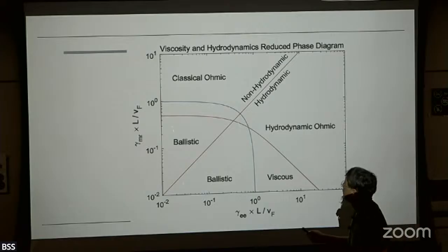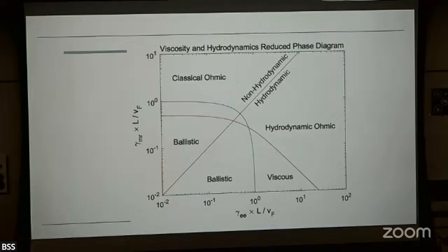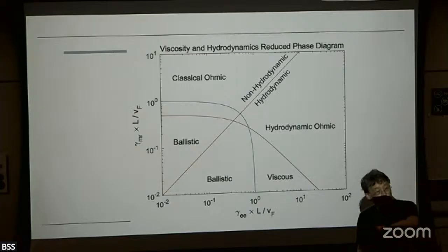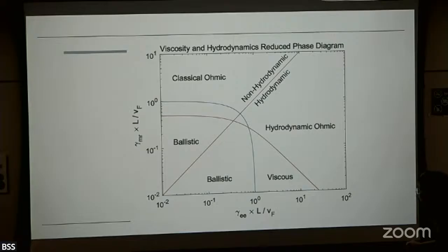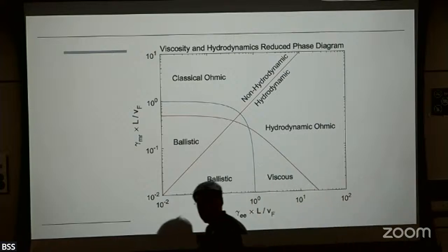And then another length scale I put down is the gauge length scale, right? Below here, the size of the system is compared with it. Above here, the size of the system becomes larger than the gauge length scale, and below here, the size of the system becomes smaller than the gauge length scale. So in some sense, I get the hydrodynamic transport around here. But truly, the strong manifestation of the hydrodynamic effect, such as wall force and the fluidic type of effect, is somewhere in this corner, above and beyond the ballistic, where yet the viscosity plays quite an important role.